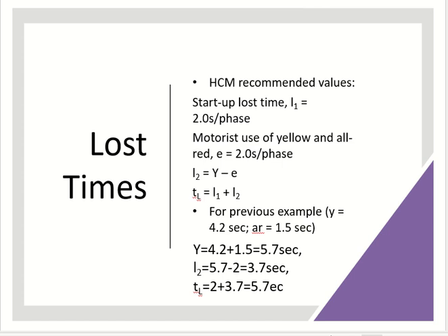Now the point is, I told you clearance interval and clearance loss time are not the same. Why are they not the same? I didn't say all red and red. The difference between them is the last part of yellow.